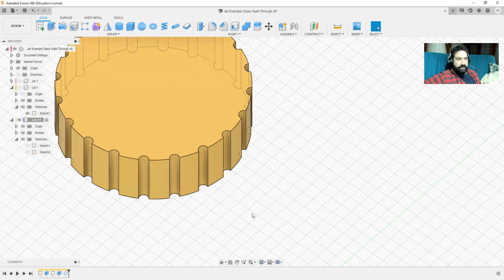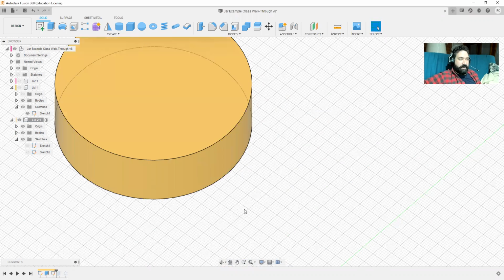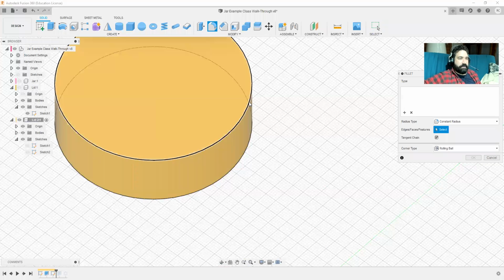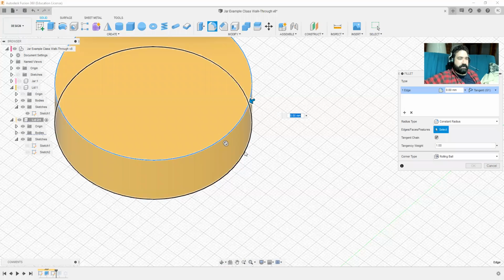Now, like I said, I repeated all of this just to show you a different way of working on that, but also, what if I actually wanted to round out this circle, round out this cylinder? Well, I can use the history slider, go back before I made that alteration. I'll select a fillet for both that corner and that corner.